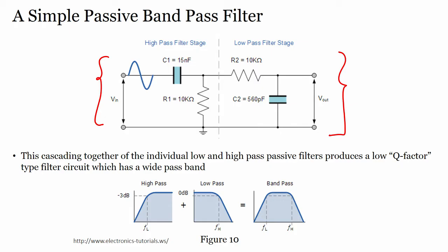Amazingly easy, is not it? Because it is so simple that by integrating the high pass filter with the low pass filter, we can get a band pass filter. Now, we should all remember that in the high pass filter there was a capacitor at the input, and then the capacitor was in series with a resistor. In the low pass filter, a resistor was in series with a capacitor, right. Output voltage across the high pass was measured across the resistor, output voltage across the low pass was measured across the capacitor, right. So, if I integrate both, it becomes a band pass filter.